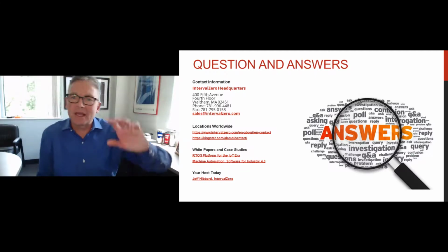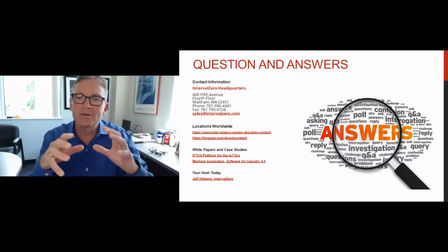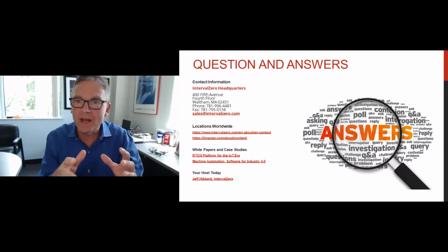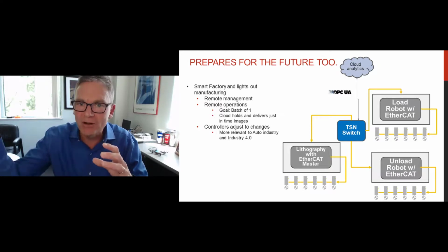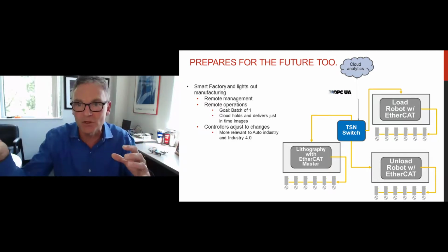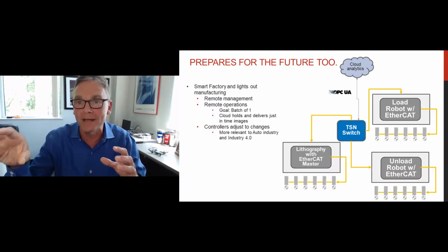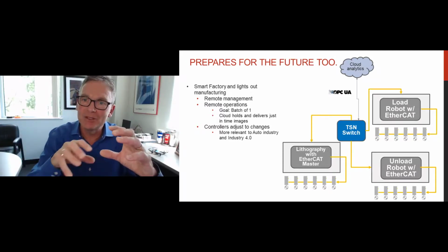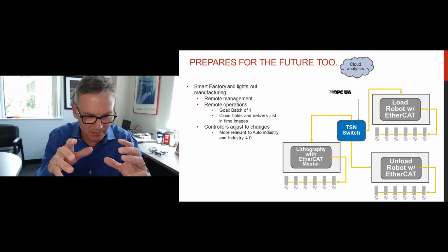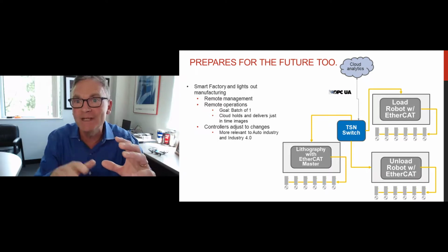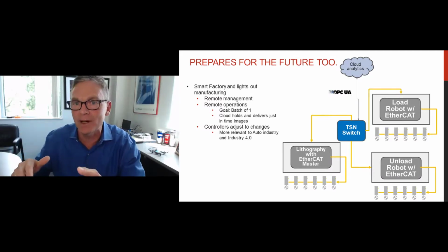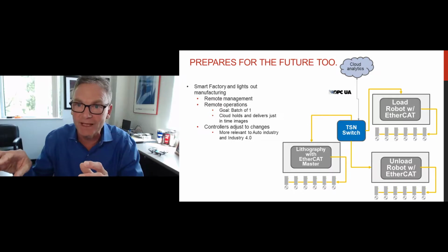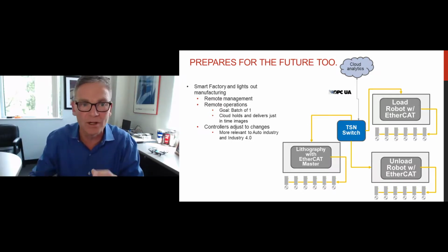Yes. The way variable data and remote procedure calls work in these integrations, when you're looking to build this kind of hybrid environment, is that you want to share information downstream to another machine. You have an upstream machine and a downstream machine, and you want to share information. Let's say you're controlling a robot. There might be situations where you do all of the calculations to figure out what command you need to send to the robot. This is a way for you to interface with a robot that has its own controller that doesn't fit into these network models. If you use TSN to send the message or other variable data downstream, the best way to do that is through a remote procedure call.